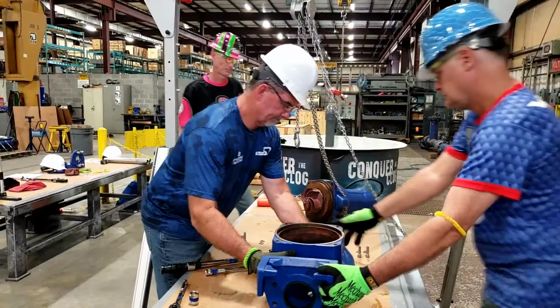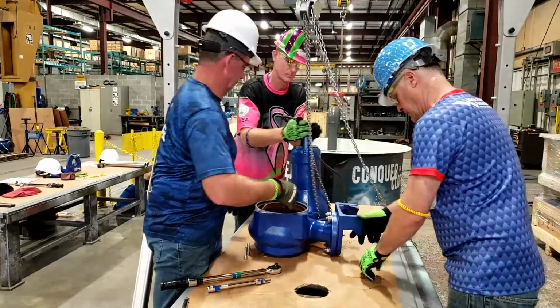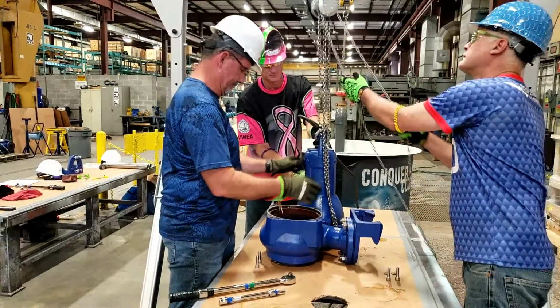Once the pump servicing, volute servicing, and wet well servicing have been completed, you can return the pump to service. Note, you may want to place the volute washers, spacers in place prior to lowering the pump into the volute. If you try to slide the washers in after the pump and volute are together, they may not go in. If you choose to slide them in after the pump and volute are together, you are doing so at your own risk of having to remove the pump to install them because they will not slide in.